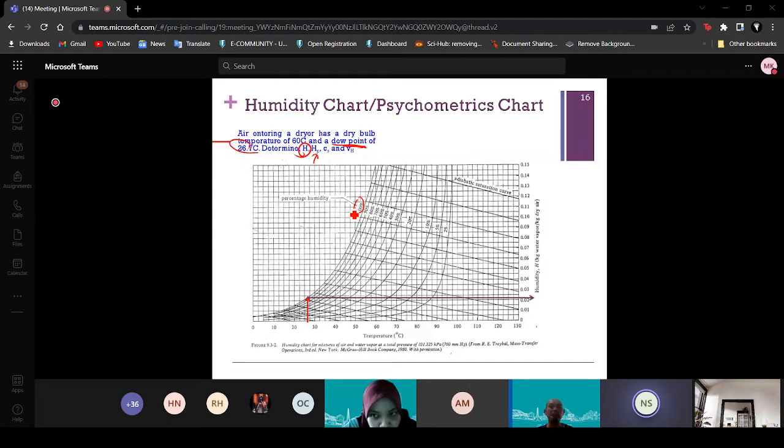But now you kena ingat your dryer actual temperature adalah 60 degrees Celsius. So what the percentage humidity at that 60? It's not 26.7. 26.7 is dew point. The condition of the dryer is not 26.7. It's 60. The 60 tu dew point dia adalah 26.7. You kena faham lah. So now dryer to 60 degrees Celsius, what is the humidity?